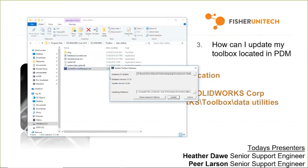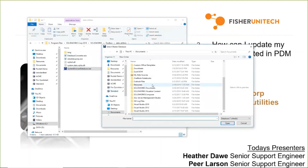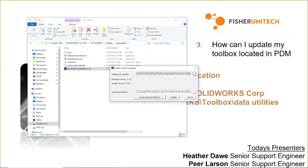If you have a toolbox predating 2012, I believe there are additional steps, and there's going to be a blog posted about this that's going to list out those additional steps. Then you notice here, it says, hey, which database do you want to upgrade? Because I changed that registry key, it's already pulled in the right one. You can browse to it if it's a different toolbox. I found that to be a bit finicky, though. I do like changing the registry key a little bit better.